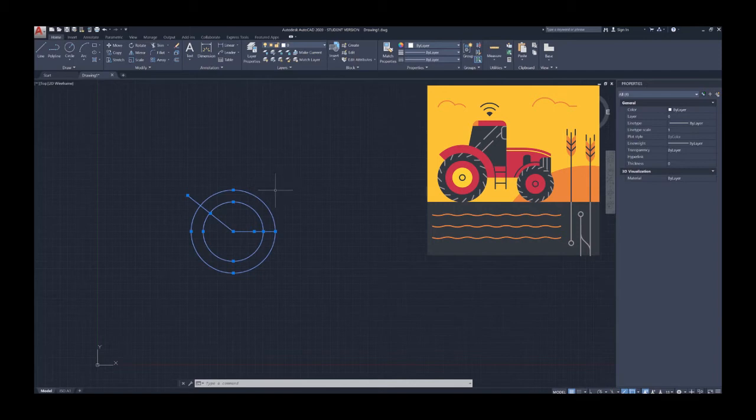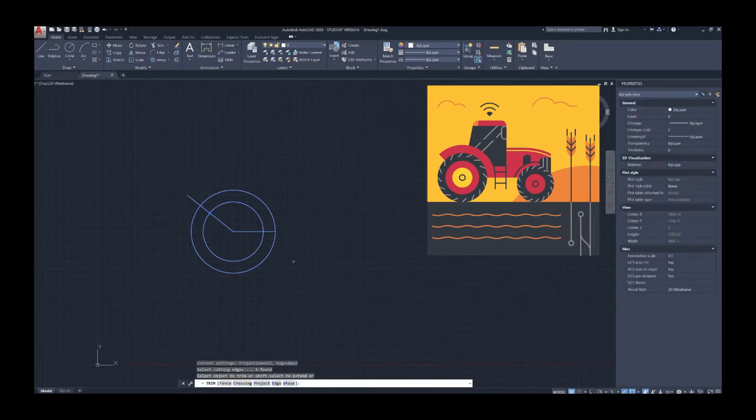We're going to trim the outside guard that I was talking about. All we do is type the trim command into the command box there, and then start selecting lines that you would like to remove. As you can see, I haven't even clicked, I've just hovered over the line and you can see that it's going to remove that line. This is a really great feature of the recent AutoCADs. So I'm going to click that line, and you can see it's starting to get those lines away.